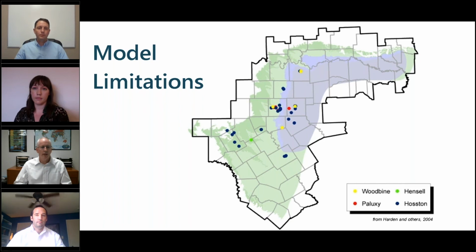If you're trying to evaluate how a model is going to respond to a significant pumpage stress, and you didn't have any pumpage stress near that in the historic calibration time period, the well-calibrated model may not necessarily give you an accurate prediction. So you need to just keep these all in mind when you're looking at your model results and how you're using them, and remember that there's a lot of limitations, and you really need to understand those.